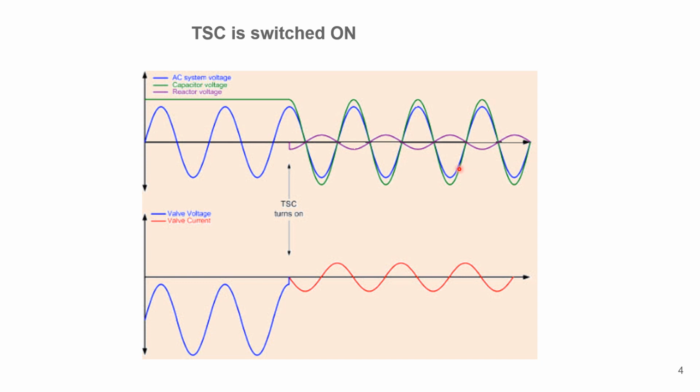The first case is when the capacitor voltage is not equal to the supply voltage when the thyristors are fired. If you close the switch immediately, an infinite amount of current flows and charges the capacitor to the supply voltage in an infinitely short time.